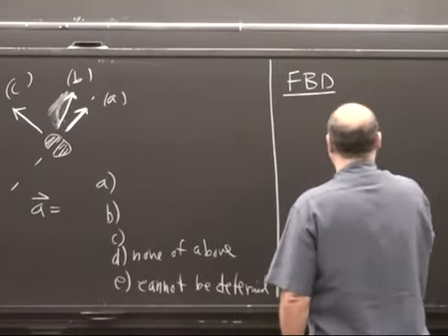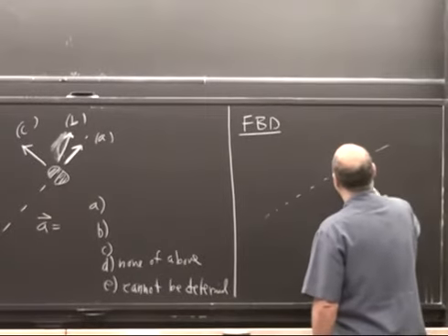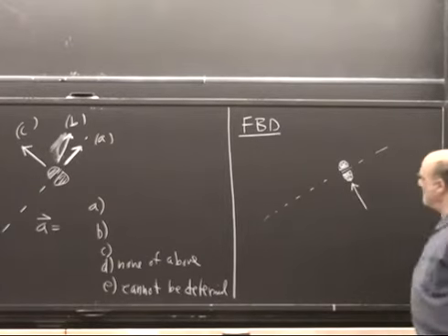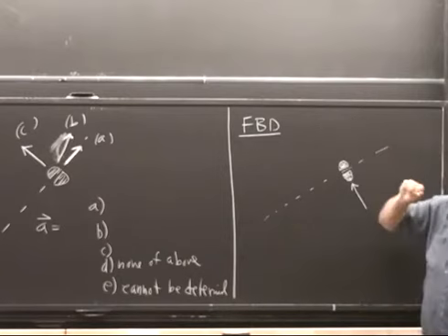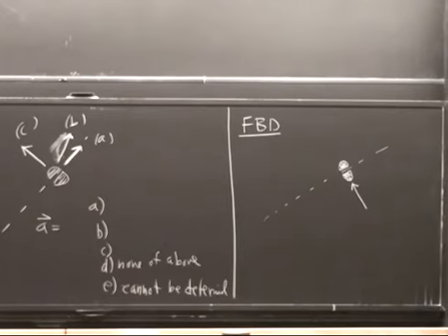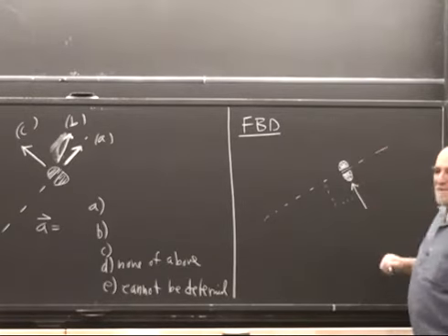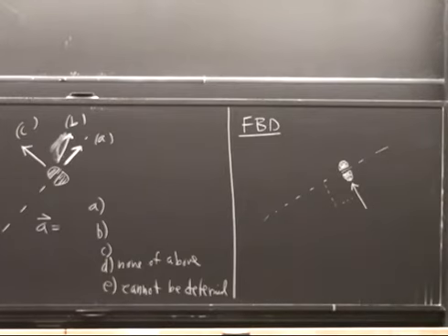Here we have this situation. The rod is like this. Here we have this mass like so. And we draw the free body diagram with a force in this direction. There could be a force of gravity, but we said gravity is negligible. Why is gravity negligible? Because I flicked it so hard that we think the other forces are so big that gravity has a small effect. If I flicked it slowly, obviously gravity would not be negligible. So we're assuming this is a right angle here. We don't draw a friction force here because we said there's no friction along the line because I put grease there, which doesn't have 0 friction, but we said it's small enough so we can neglect it to do this calculation.